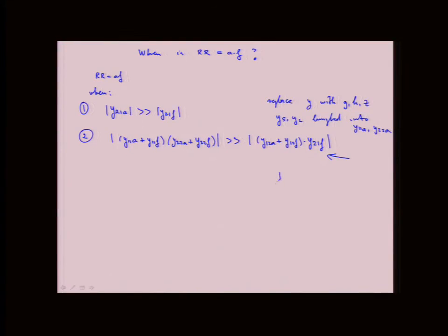So if you take the Y21A VI, and you measure this as the return current, and then you apply I test, Y22A, and the rest of the circuitry is the same as in the two-port representation. But by going through this loop, you can actually calculate the RR, return ratio of this source, Y21A. And when you do that,